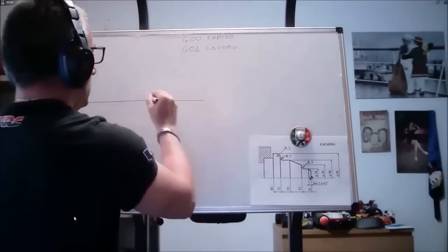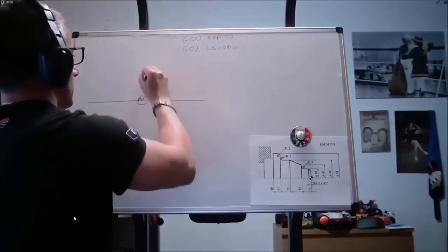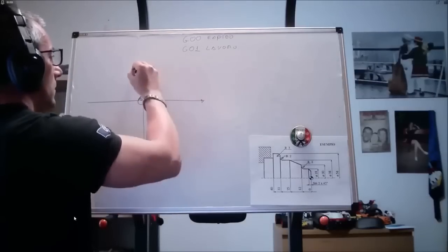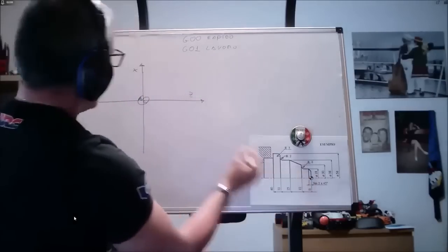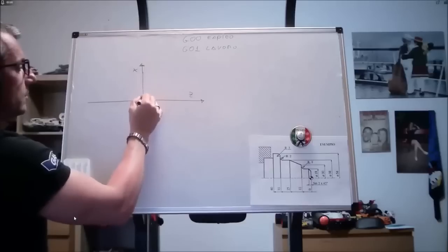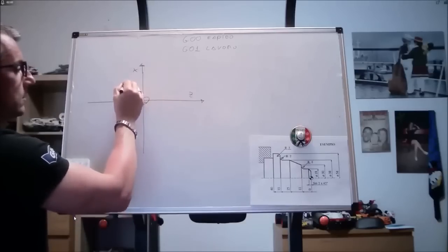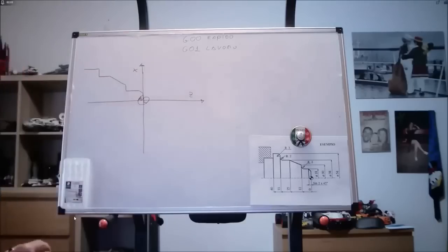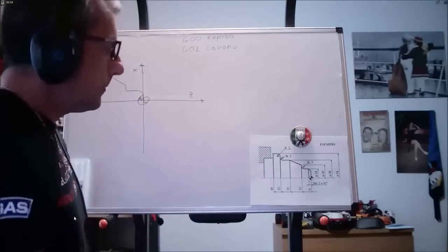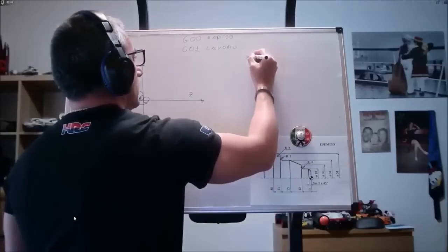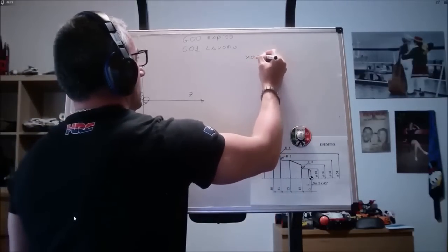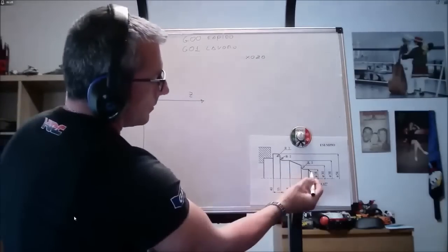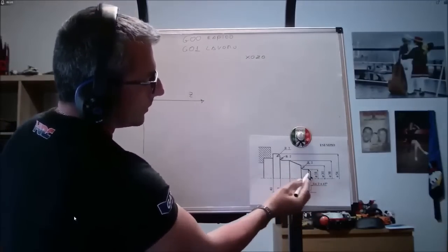So, this is our Cartesian coordinate system, x, z. As you can see, the origin is here, and my piece is located here. So, the first dimension we need to reach is x0, z0. After that, we need to move here. This bevel is 45 degrees.